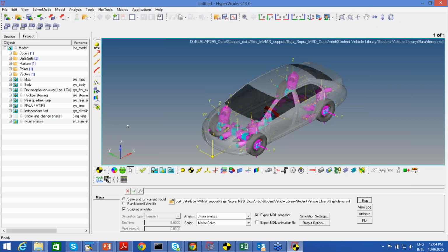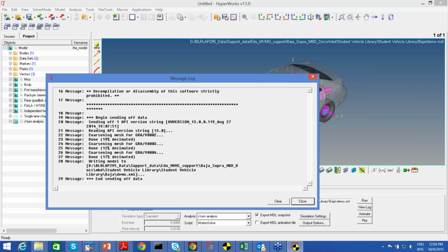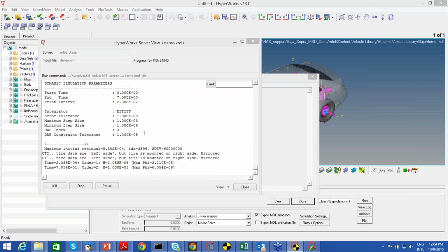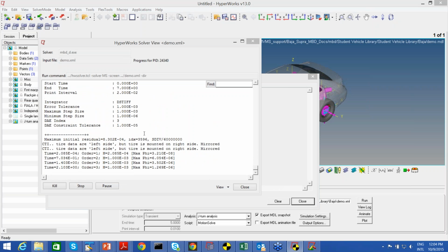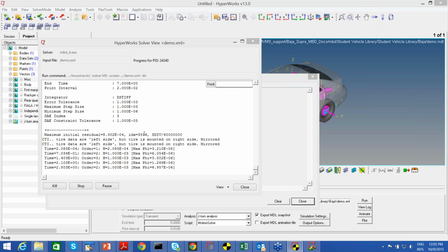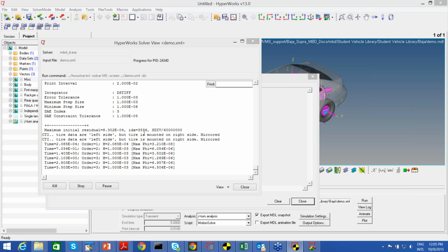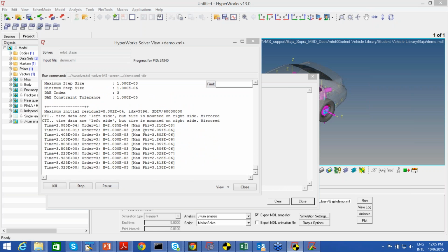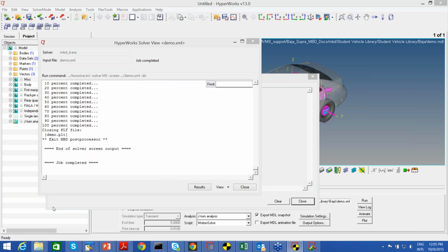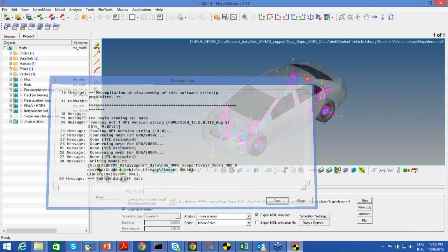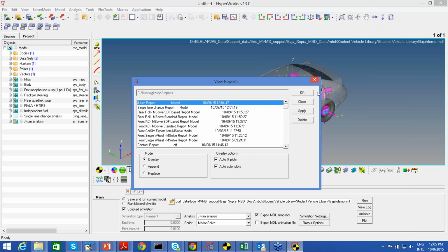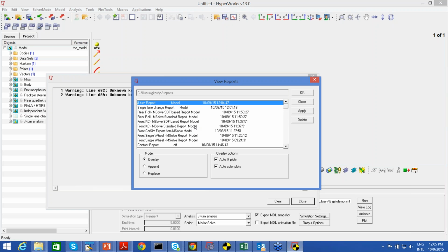Okay, so here I am now running the J-turn analysis. We'll observe the behavior of the vehicle in this event, and we'll observe some standard outputs of this J-turn event as well. The significance of this on the vehicle, we can observe virtually, and then we can understand that physically also on the ground, in a proving ground test. Okay, so my J-turn event analysis is also done. I'll go to the analysis, see view reports, standard report template. I'll load the report also.